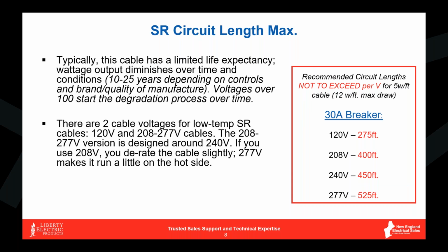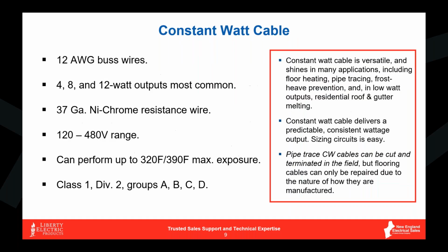So just as a quick hit guide for how long you can make a 5 watt a foot cable circuit length, here are your different voltages and how far you can max out those circuits based on your voltage. And we're going to touch on this again, so we'll be visiting it a little bit later on in the presentation. Constant wattage cables are different. Constant wattage cables are much easier to size the circuits. They just are what they are.